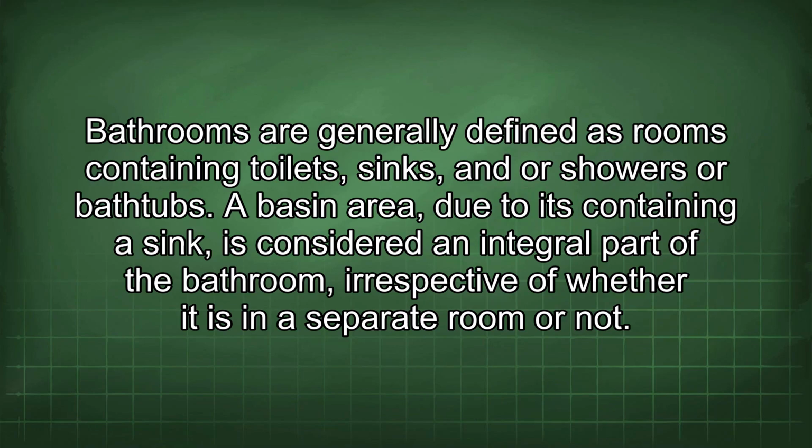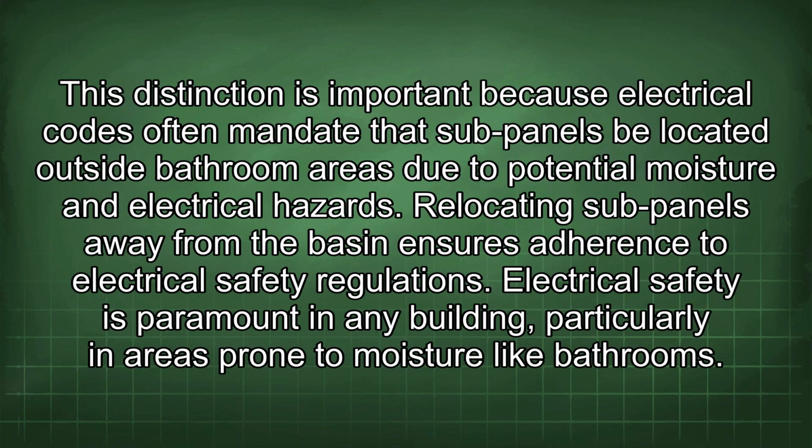Bathrooms are generally defined as rooms containing toilets, sinks, and/or showers or bathtubs. A basin area, due to its containing a sink, is considered an integral part of the bathroom, irrespective of whether it is in a separate room or not. This distinction is important because electrical codes often mandate that sub-panels be located outside bathroom areas due to potential moisture and electrical hazards. Relocating sub-panels away from the basin ensures adherence to electrical safety regulations.